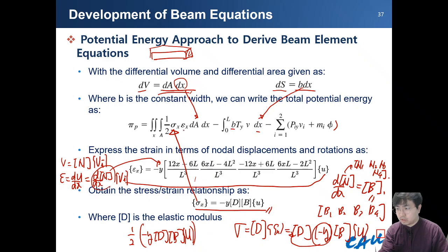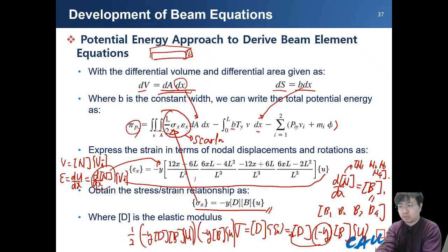So one half times the stress, and this is the stress, and this is the strain. The strain also has the same form, B u. So at this time, how can you use it? I already mentioned that this value is a scalar, matrix or vector. This is a scalar, because energy is a scalar value, so after calculating this part, it must become a scalar. The integration cannot change the vector or scalar form.